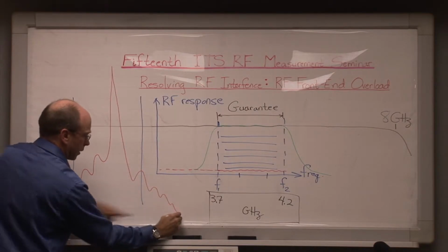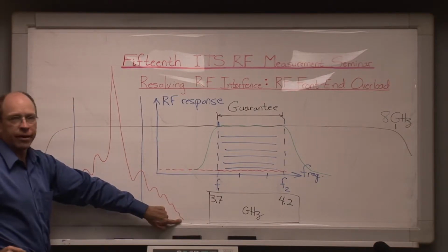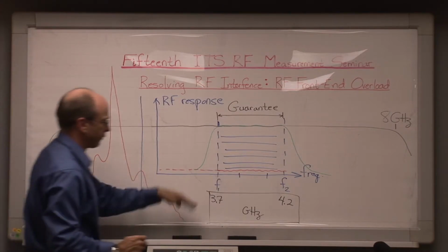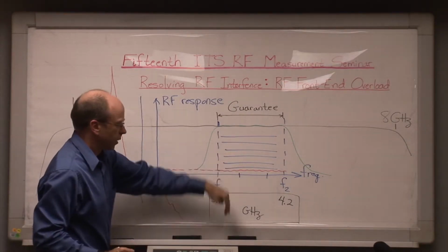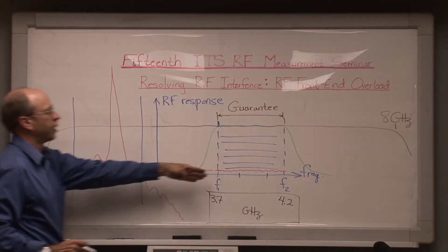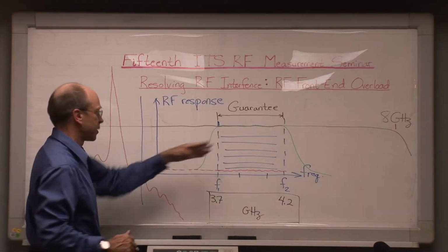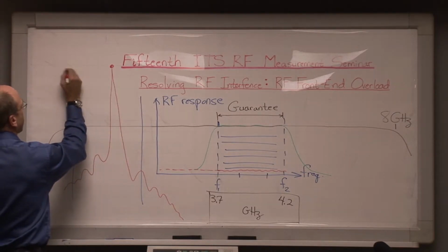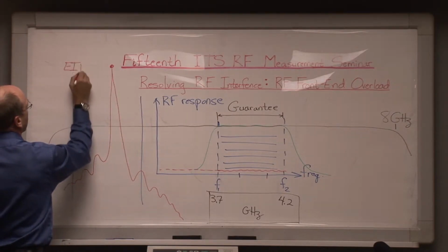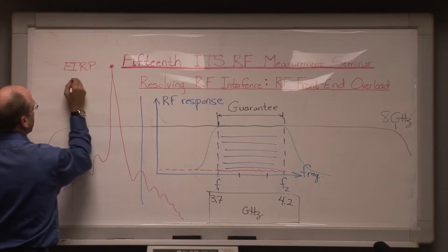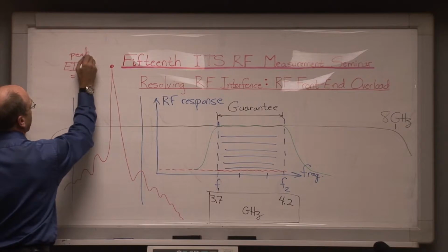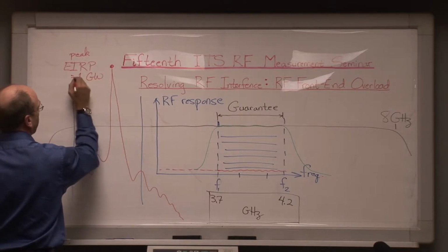And we'll imagine that these emissions, the unwanted and spurious emissions, out-of-band unwanted spurious emissions, drop way off from the system by the time it gets to this receiver band, so low that we can't measure them in that band, even if we get up close to the transmitter, which happens. But that it has a fairly high EIRP at its center frequency. We'll say maybe the peak EIRP might equal, for example, something on the order of a gigawatt.